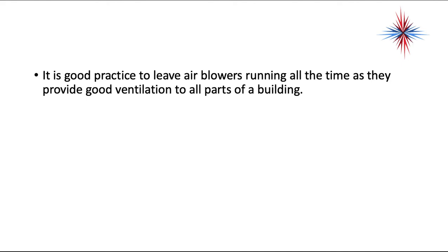So that is basically what we can look at about our ventilation, air movement, air flow. Again, important things to remember: air has weight. This weight of air takes work to move. Air will stratify if the air is not being mechanically moved. Hot air rises, cold air falls, and we have to take that all into account when we place ductwork and calculate air requirements. You have to pull ventilation in from the outdoor environment and check your codes to see how much.